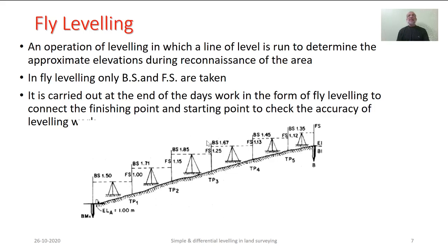One must understand one more concept that we will be discussing again in the subsequent slide, that don't get confused about this particular determination of approximate elevations. Sometimes, for example, if we are carrying out some kind of leveling operation and the GTS benchmark is placed quite a distance away, and if we wish to carry the reduced level of that particular GTS benchmark up to the site where we wish to work, at that time also fly leveling can be conducted.